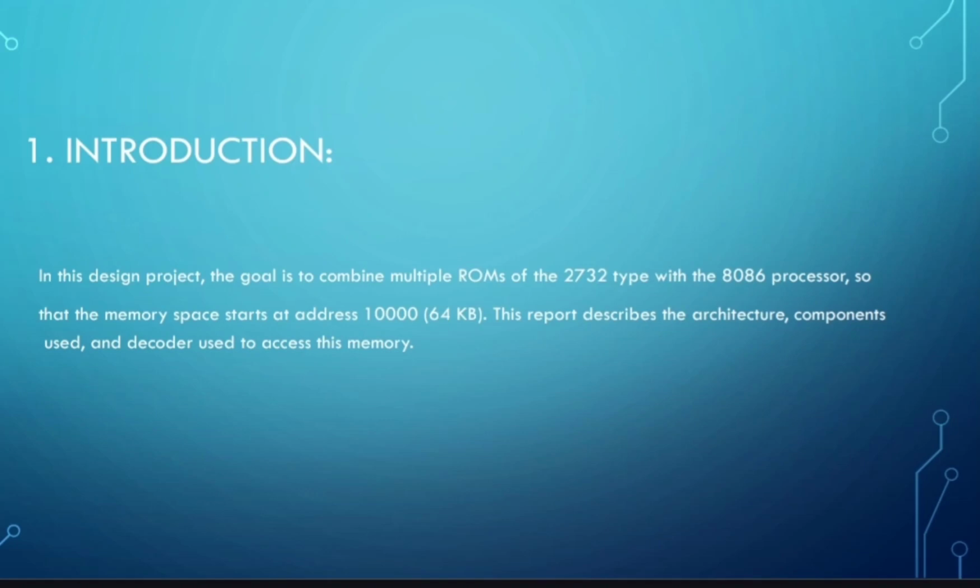Assalamu alaikum. In this video we will review my special report on connecting multiple ROMs of type 2732 to an 8086 processor, and we will use this PowerPoint file to facilitate the explanation. In this design project, the goal is to combine multiple ROMs of the 2732 type with the 8086 processor so that the memory space starts at address 10,000